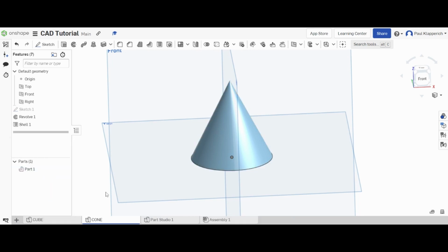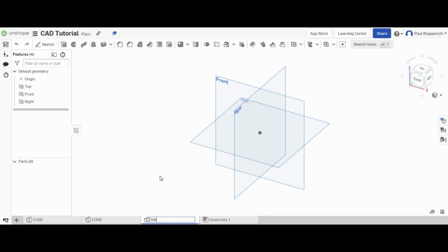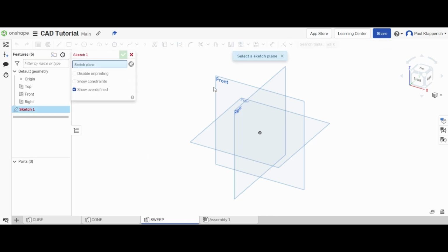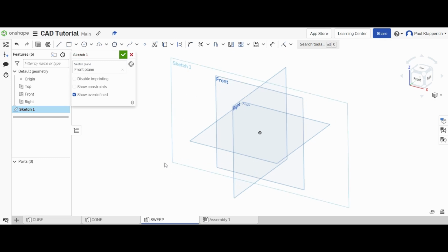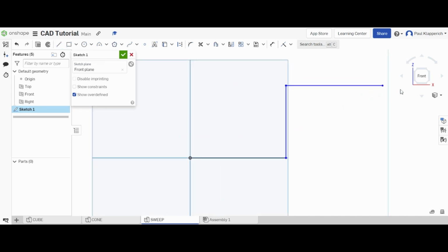Let's create a new part. We'll call this one sweep, and you'll see why. All right, first thing, create a sketch. We're gonna make kind of a gummy worm shape, if you will. Not too hard. So you'll see what I mean in a sec. We're gonna make basically a curvy pipe, and it's gonna follow this shape right here. We're gonna make a tube follow this shape.